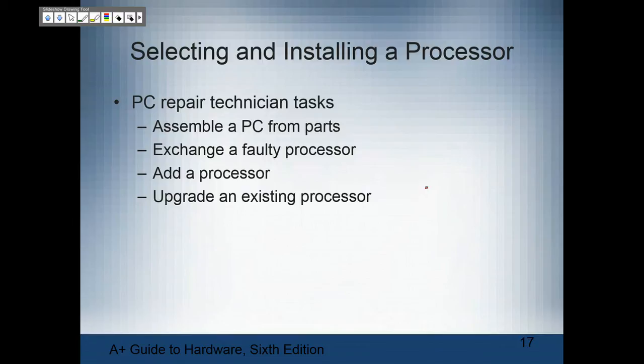As long as you know what you're doing, you disconnect it, take the processor out, put the processor in. The key here is going to be getting it lined up, and pin 1 is going to be marked so that you know where it goes. Years ago, I was doing this class, and we took apart some functioning computers because we didn't have all the stuff laying around that we can just take apart and put back together, not worry about because they don't really work. And somebody took apart a machine.